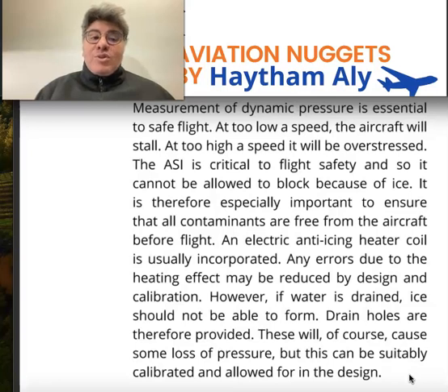It supplies the airspeed indicator and machmeter only. The altimeter and vertical speed indicator need only static pressure, not pitot. The attitude indicator, turn and slip indicator, and heading indicator are gyroscopic instruments. They are not pressure instruments.